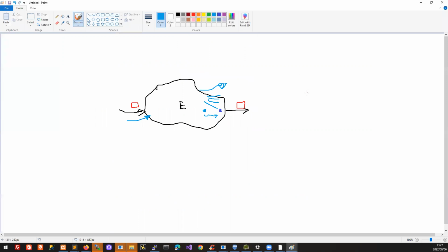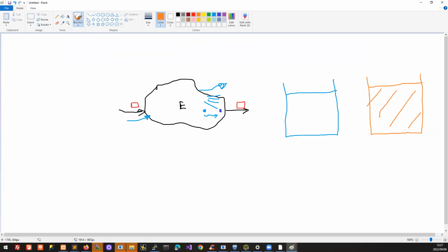So if you have, and this is the example we drew yesterday, if you have a glass of water and if you have a glass of honey, then of course the honey has a higher viscosity. It offers a greater resistance to any kind of deformation. And what it also means is that if you have a stream that's flowing, let's say it's a stream of honey here, then your stream, your center line, the fluid at the center line position, that's typically the fast position, and then near the wall is slow because of friction with the wall.